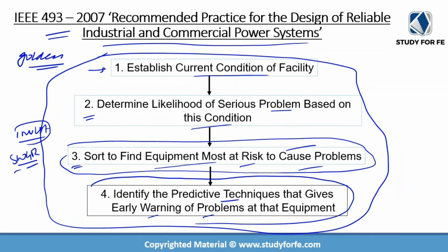And similarly for the switchgear, you can have temperature monitoring on the bus work. You can have temperature monitoring around the circuit breakers, and you can monitor it on a live basis, or you can have some sort of thresholds established. There are a lot of different solutions that are now available. Then you will be able to identify that, okay, this equipment is about to go, and before it reaches the end of life, you can replace it or come up with some other mitigation measures.